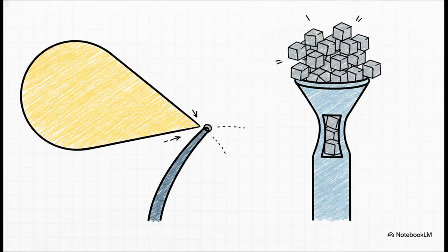However, to really thoroughly understand the tech, we have to look at the limitations too. First off, think back to that tiny 2 to 15 micrometer core of the single-mode fiber. Trying to perfectly align and couple a light source into a target that impossibly small is just highly difficult, and it requires some seriously expensive precision equipment. Secondly, while sending one single ray at a time prevents the distortion we talked about, it inherently limits the overall volume of information carrying capacity you have at any given moment.